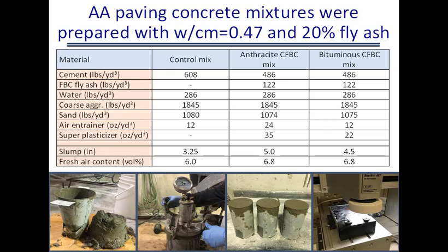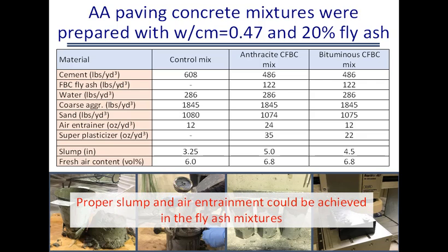So even though these fly ashes have high loss on ignition, with proper use of air entraining admixtures, and if you compare the air entrainer dosage, they are not excessive. They can be air entrained, and they can produce a good air concrete. So proper slump and air could be achieved.